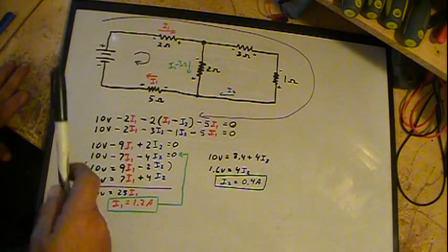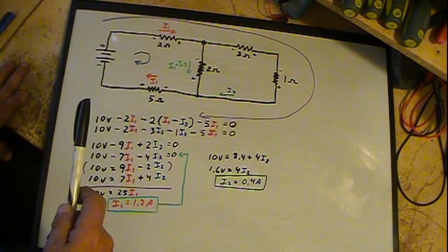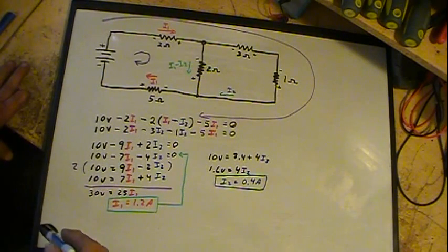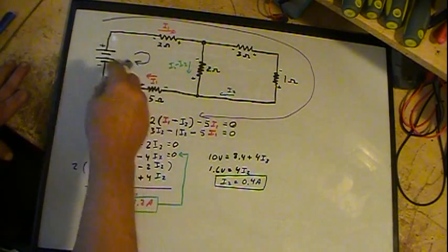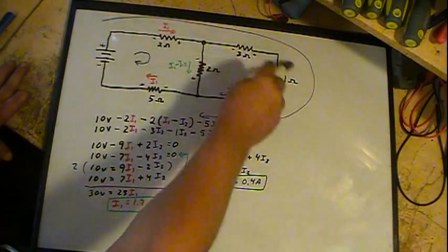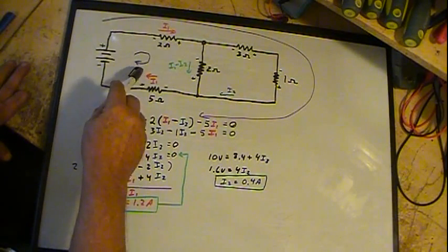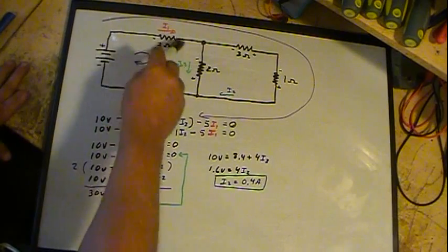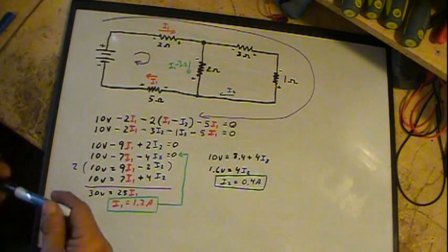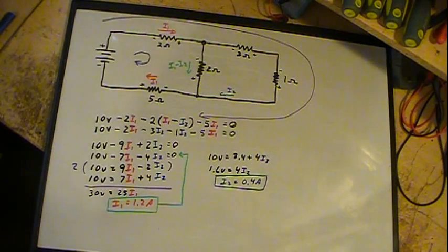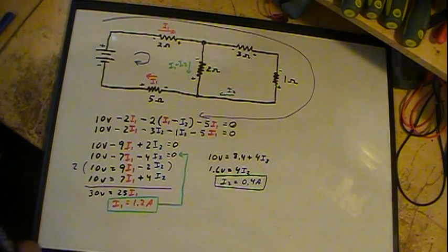Now, the other rule or law is called the loop law, and it deals with voltage drops. You establish a loop like this purple here and this outer loop. It states that the algebraic sum of all the voltages, the voltage drops in that loop, will add up to zero. Okay, what does that mean? Well, basically this circuit here, since we only have one supply, we're not really going to concern ourselves a whole lot about the junction rule as much as the loop rule.